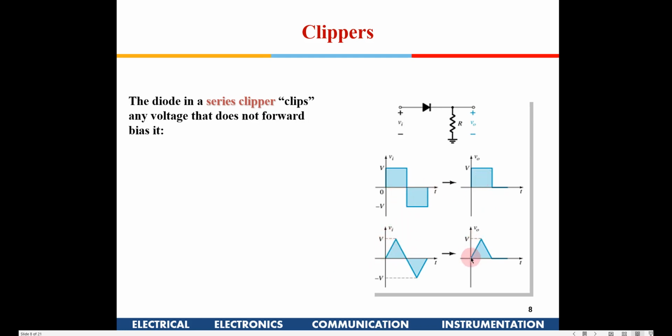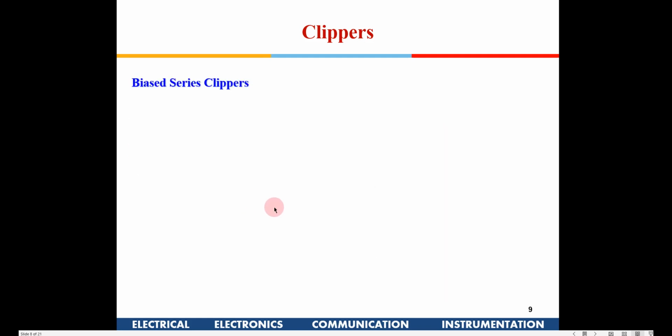So this is a triangular shape, this is again a triangular. Here again in this particular problem, the diode is considered to be an ideal diode. So the reverse polarity less than 0.7. If you have to consider it as a real diode, then we got to cater for the forward bias. Whenever the input signal is greater than 0.7, only then it will conduct. So that needs to be taken into consideration if we are talking about a real diode.